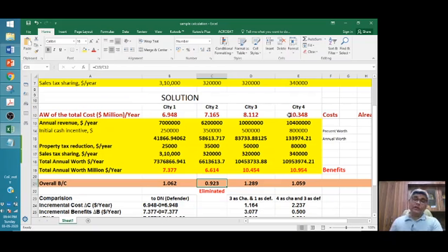If we get somehow different values, then we have to arrange the cities in such a manner that the minimum cost project will appear first and the maximum cost project will appear at the last. Now once we calculate the B by C ratio, the very first step is that we will eliminate the city where the B by C ratio is less than unity, or less than 1.